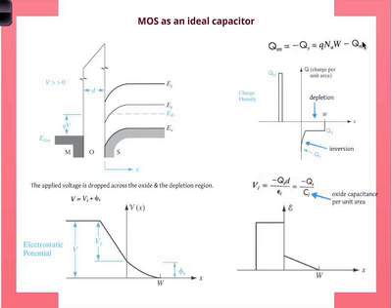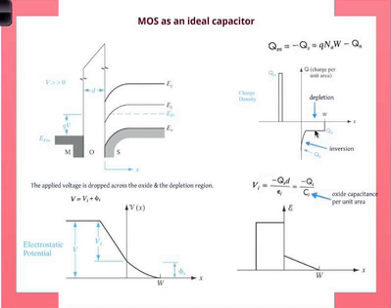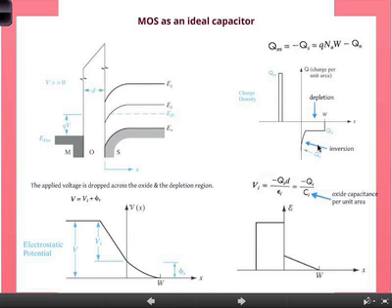So you have a big charge density right at the interface of the metal and the oxide. No charges in the oxide. And then you have charges coming from the inversion, which is electrons. And you have charges coming primarily from the depletion, which is shown here, which is from the uncompensated ions, minus the electrons. So you have a situation like that.